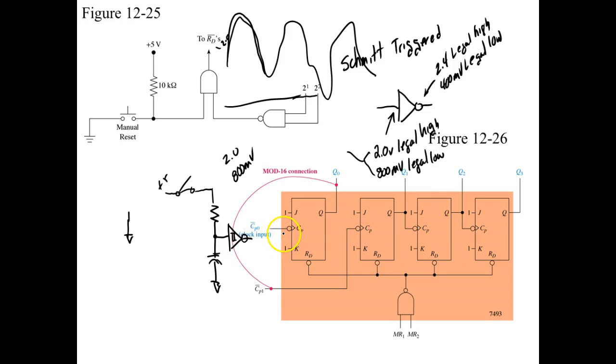You understand? And we'll look at this. We see this a lot inside devices that gives us an automatic reset every time we power them up. This is shown in the lab, but you have to use basically a Schmitt trigger, because this one over here might reset at a different time than the one right beside it, right? You understand that? So Schmitt trigger inputs.